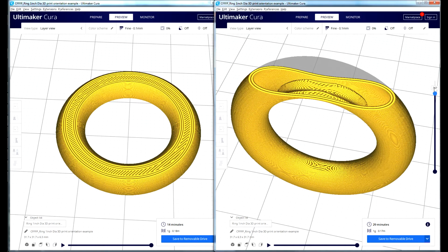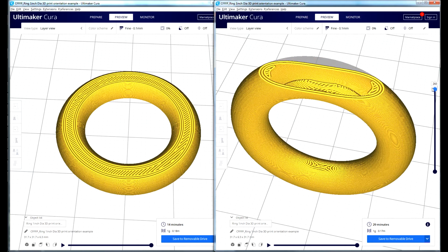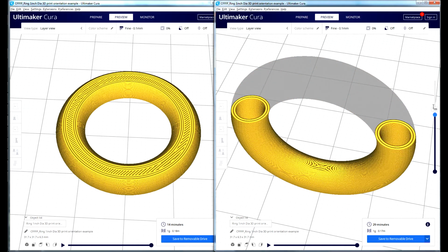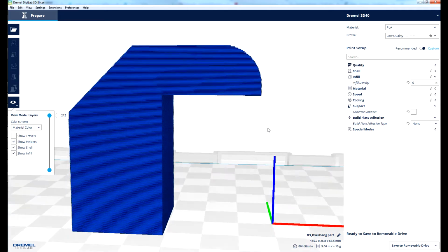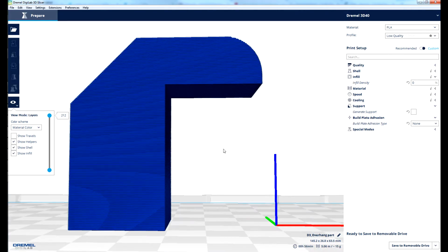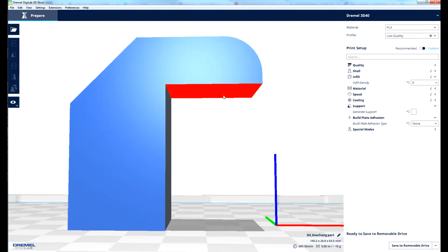There are other ways to improve a part's strength beyond this. We will explore one feature later, but just know 3D printing does have its limitations. Orientation also affects support structure. You cannot overcome gravity when printing. You cannot print without a previous layer underneath.